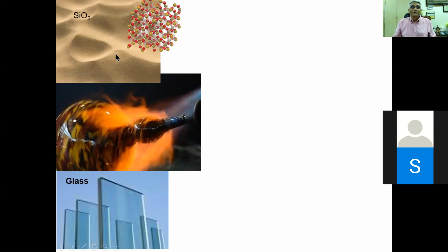And in some parts of the world, it's very interesting that the same silicon dioxide, you see small crystallites, millimeter-sized crystallites. That means these beach sands are so pristine. There are also all the requirements for nucleation to happen between different particles, leading to coalescence into larger particles. That means there is no external disturbance when this process is happening, but this takes several years, right? So it happens in uninhabited places, where a continual formation of small particles into larger particles can happen. It's all about thin film growth, polycrystalline materials growth, single crystal growth, all about nucleation.